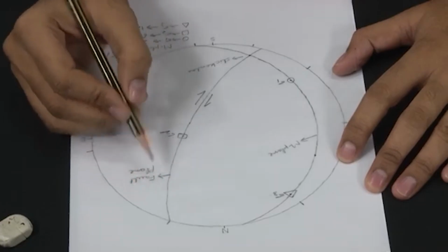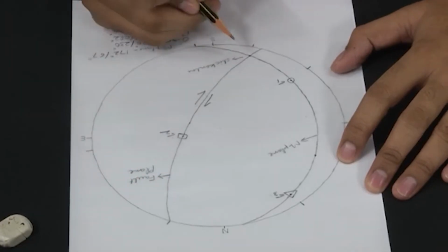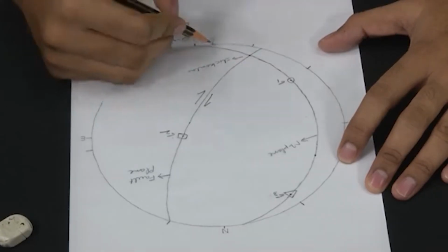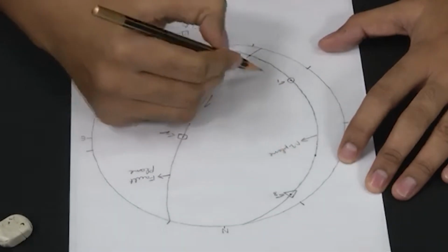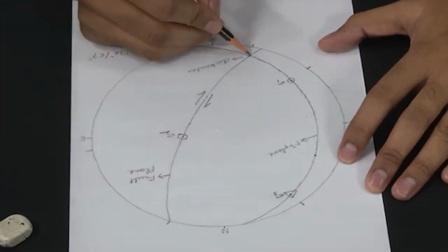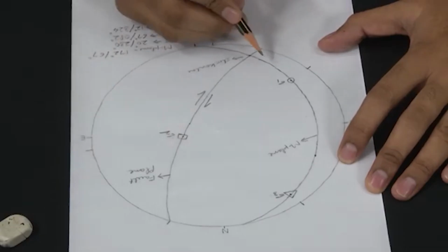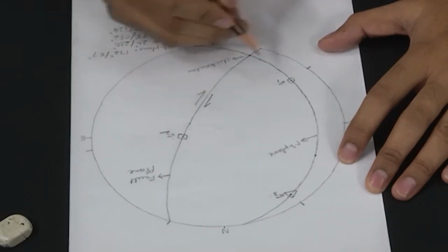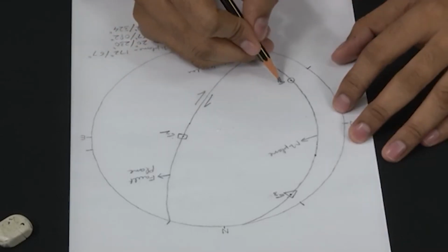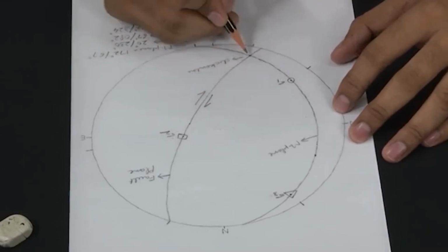The strike and dip has been given, as well as the trend and plunge of the slickenside line. So, what we did was plot an M plane perpendicular to this fault plane passing through this slickenside line. Then for a dextral strike-slip fault we have to count theta, which is the angle between the maximum stress sigma 1 and the slickenside line.